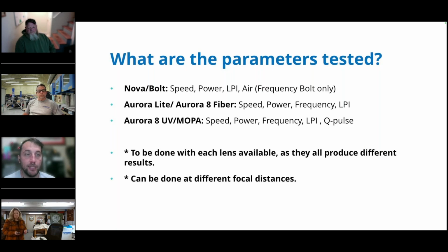Even if your set speed, and a lot of people say, oh, I've got it running 1,000 millimeters per second, and I'm engraving quarter-inch tall text. I'm scoring this text. Like, no, you're not. That's too small, so you're already going slow. But even on something ornamental size, whenever it gets to the tight curves and sharp corners, you're having to slow down, right? It's physics. There's kinematics involved, and you must slow down to make a hard left turn. But from what we've seen, it does not.